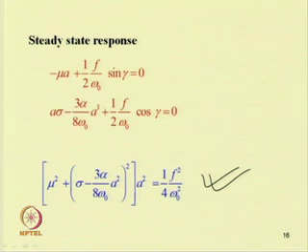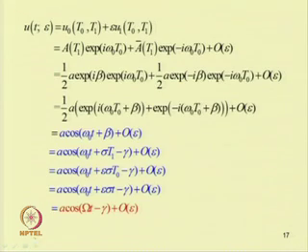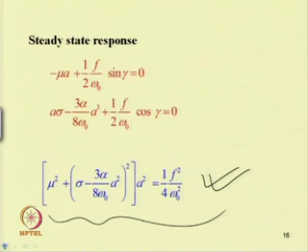So, this is the frequency response equation for the steady state condition. In this case we have obtained an equation which is quadratic in terms of sigma and sixth order in terms of A. So, easily one can solve this quadratic equation to get the frequency amplitude relation, and also one can have the response, u equal to a cos omega t minus gamma, where a is the amplitude. This amplitude one can obtain by using this expression.